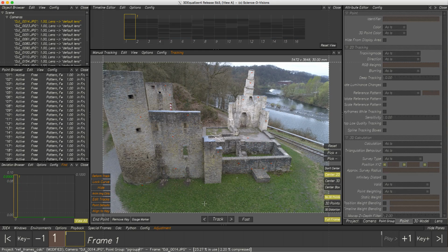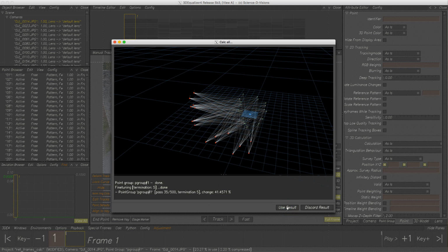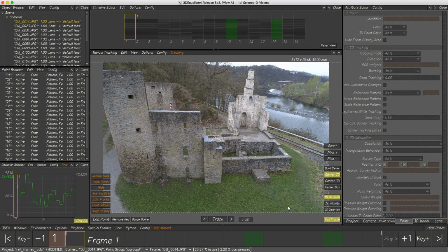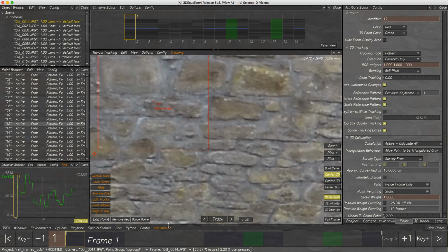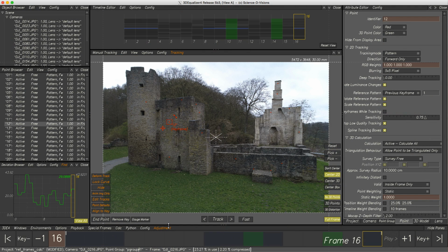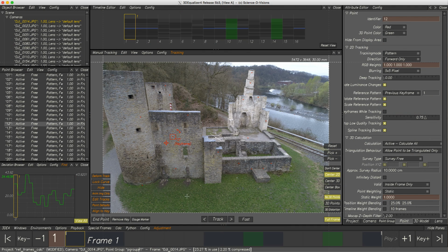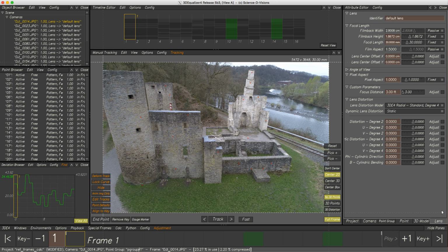Very good. So, calc the project. Well, deviation clearly shows a problem with our project. What happened? Tracking errors can be excluded from a potential issue list. When checking a tracking point more closely, its high tracking precision can be seen. It seems the lens must cause the high deviation since it's still set to default. We have to adjust its parameters to the footage.